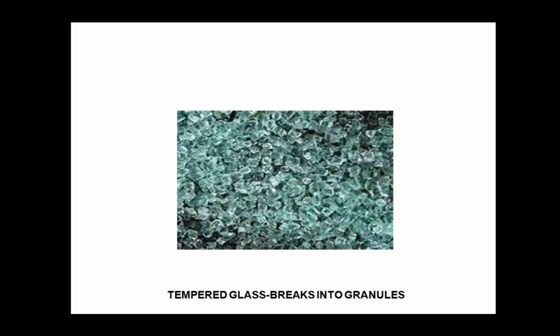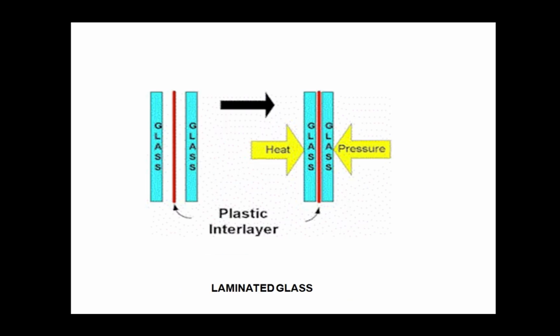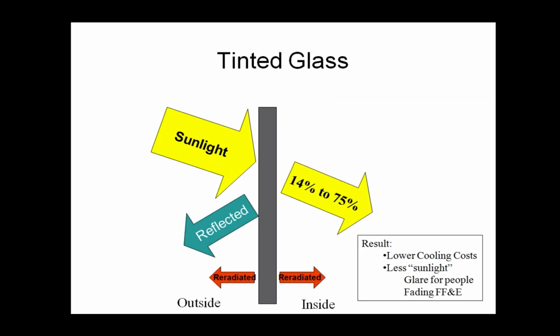Alright, so this is kind of what it looks like when tempered glass breaks into granules, so you might want to have tempered glass that's laminated. Okay. So as you see here, the lamination is actually on the interior between two sheets of glass. So whichever side breaks or heats or somehow, basically both are stuck to that singular layer.